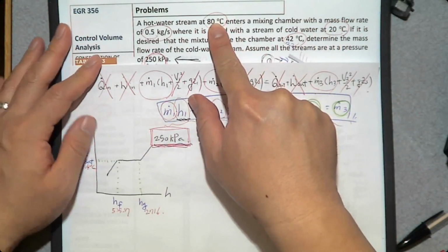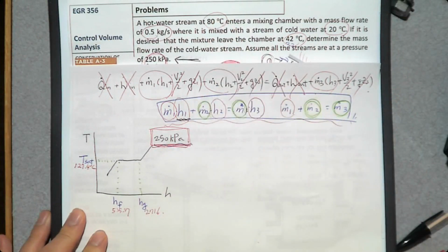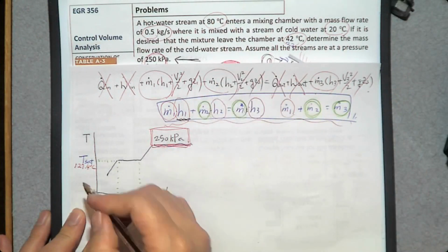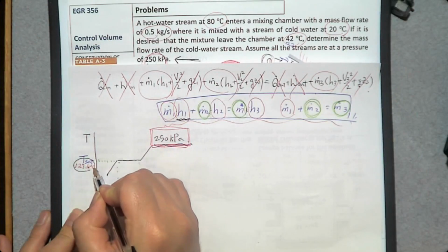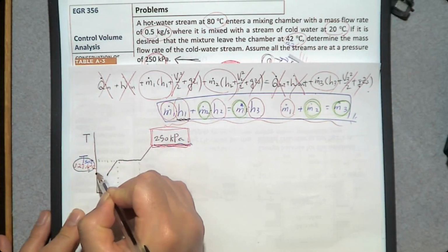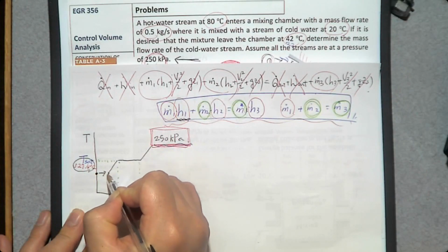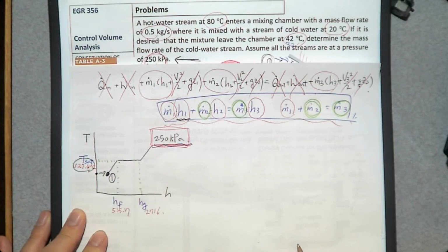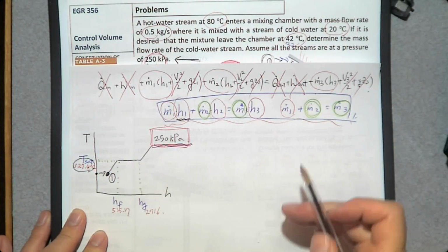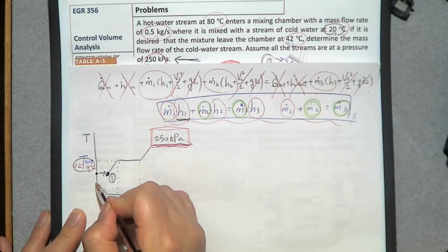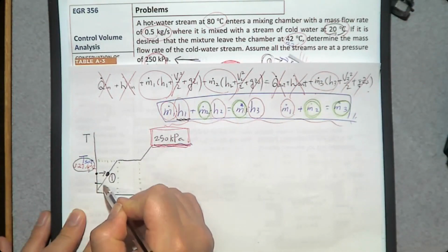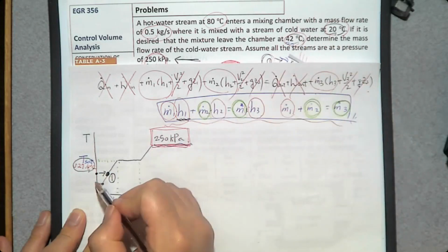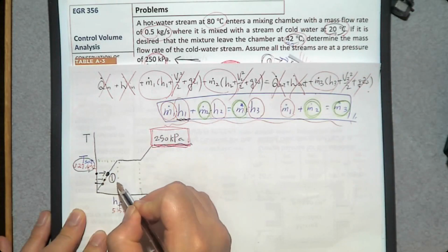Then, what is the temperature at each inlet and the exit? The highest temperature is going to be 80 degrees Celsius. So where is 80 degrees Celsius? Lower than this temperature. So 80 degrees Celsius is somewhere around here. So the only possible phase change process is going to be number 1, compressed liquid. What about 20 degrees Celsius? Here, T number 1, 42, somewhere here. So still number 1.